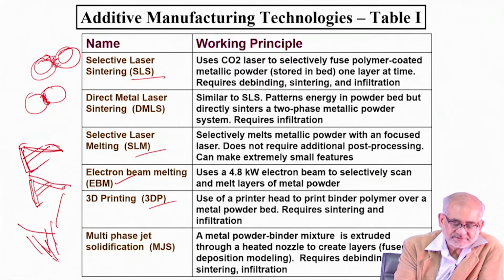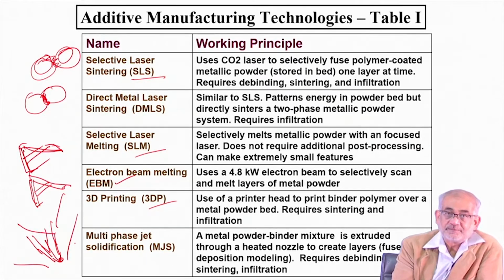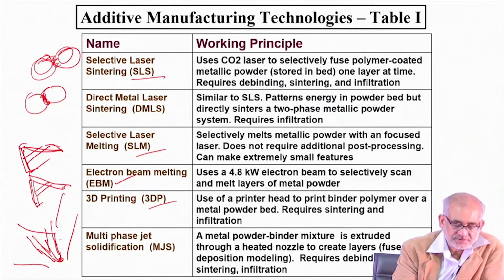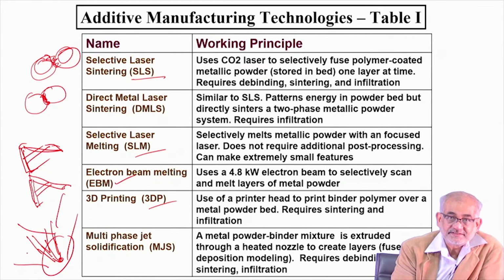So if the laser beam is incident here, the powder can also come in a concentric manner to the same focal spot. This is a lot better than having laser and powder coming from two different directions. In fact, these days with a fiber laser delivery system, this possibility has become extremely feasible.